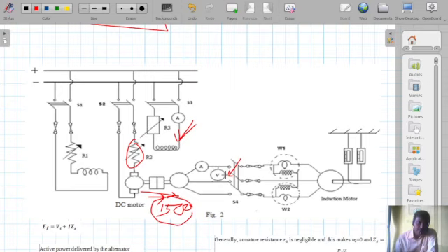Okay. Now in the same way we can increase the mechanical load also to take more active and reactive power. So intentionally we will apply more mechanical power, so active and reactive power will be increased. So this voltage and the frequency or speed will again drop.